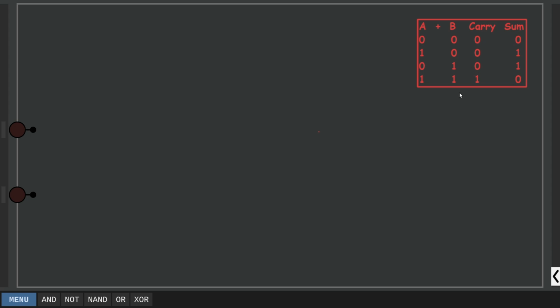If you see this area, which is carry, and if we recall some knowledge from the last video, this is actually the value of an AND gate. An AND gate outputs 1 only when both bits are 1. So in A plus B, if both bits are 1, then output will be 1. But these values are actually from our last video, the XOR gate.